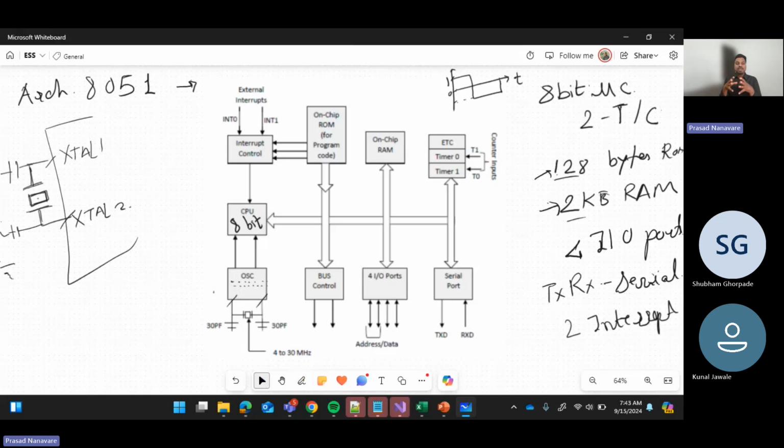When an electrical signal is provided to the crystal, it gives mechanical vibrations, and conversely, those mechanical vibrations are used to generate an electrical frequency out of it. So we are getting some electric frequency out of these pins of the microcontroller, which we are going to convert into a constant clock cycle.